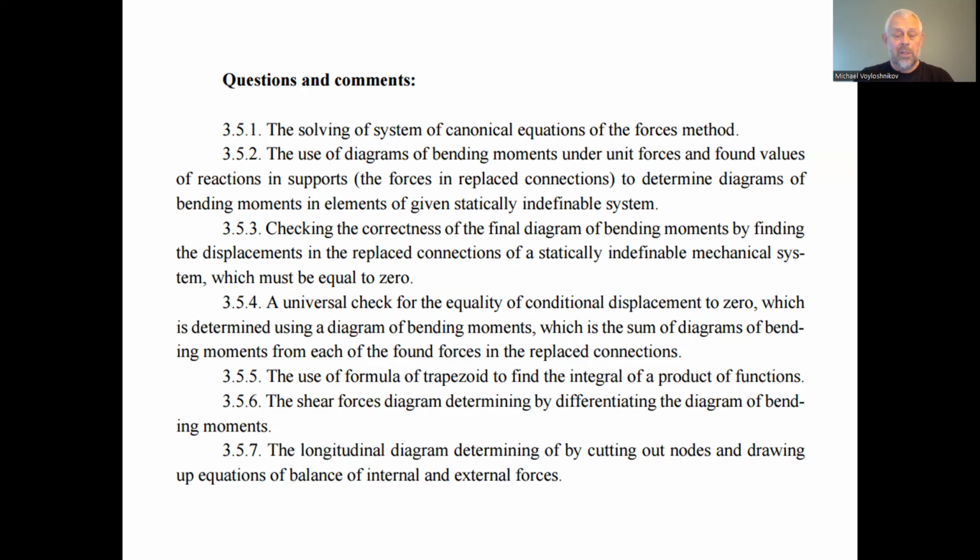So in the directions of the support reactions, we may do the check and find the displacement under the action of the bending moments in accordance with the final diagram of the bending moments under the action of the external load and found support reactions. To do that, we can use the Mohr integral to find the displacement. If the displacements are zeros, the check of correctness is good.